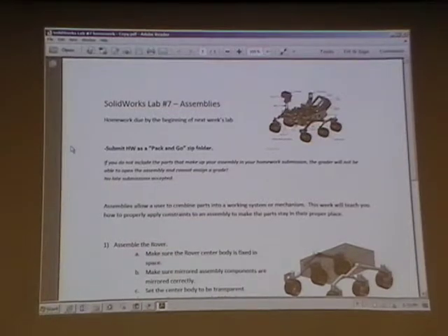The other tool that we're talking about is Sketch Block. That allows you to take a sketch that you've created and save it in its own independent file. And you can then reuse that sketch block in your part over and over, or in different parts over and over. So this could be useful if, for example, you're working for a company, or maybe you own your own company, and you created a company logo in a sketch, and you want to put that logo into every part that you manufacture. Well, you could just save that sketch as a sketch block, and then you can bring it into all of your different parts very easily.